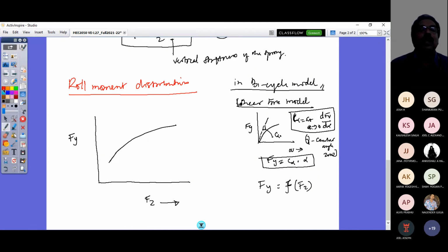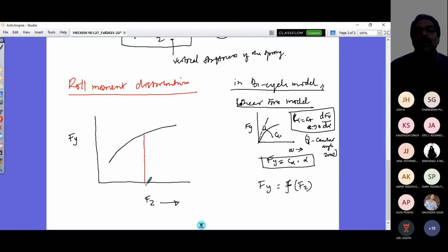So what do you understand from this? If I take a particular value of normal load, say 800 pounds, for a case study vehicle available in the textbook, and this is the normal load on a particular tire wheel, then it can correspondingly produce a possible lateral force of 760 pounds at a particular slip angle, say 5 degrees.